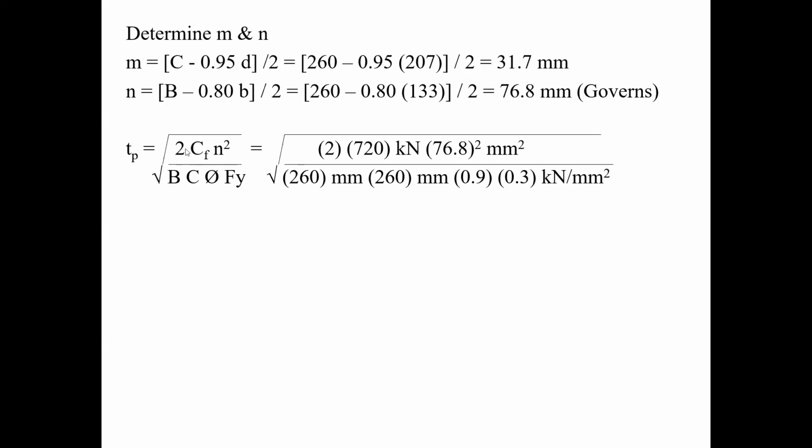So in other words, this calculates the bending moment. And then of course, you're making sure that the MR value based on your T value is greater than your MF value. That's all this formula is. I might show you this when we're going to be doing the exterior, the base plates for the exterior columns. I might go into a little bit more detail to show you how these things actually get calculated.